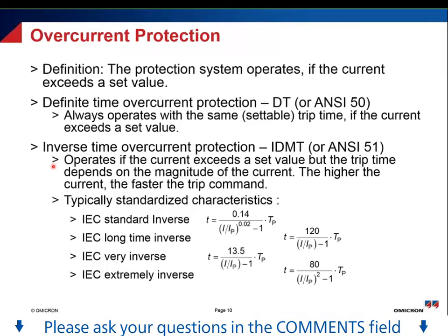Well, there is a huge amount of different inverse characteristics that can be used, but typically they are standardized. So in this case, you can see we have, for example, standardized by the IEC, different characteristics: the standard inverse characteristic, the long time inverse characteristic, the very inverse, and the extremely inverse. I also show here the formulas how to calculate the trip time based on the standard.